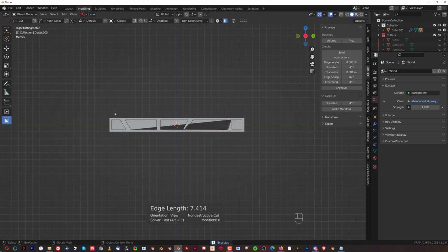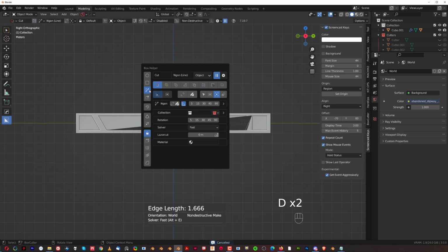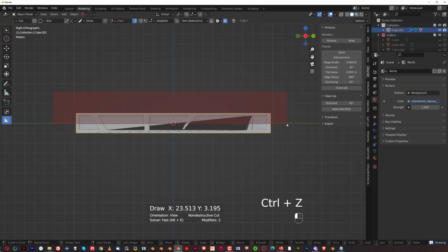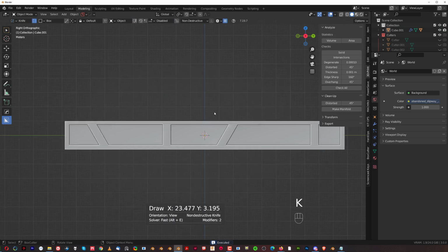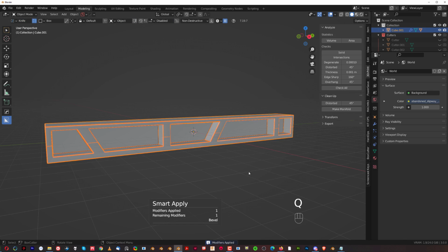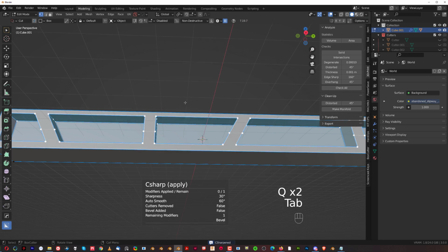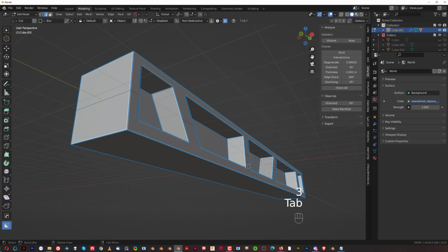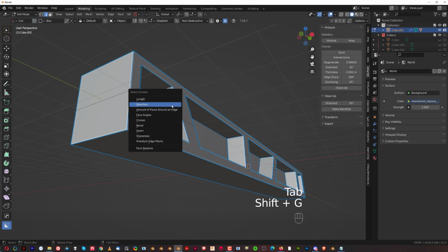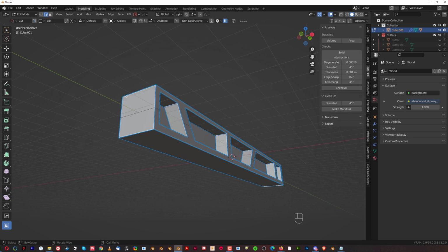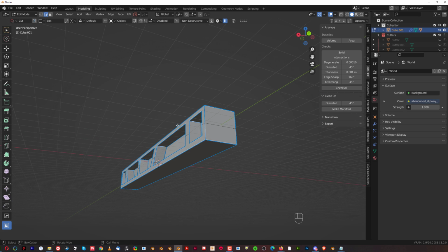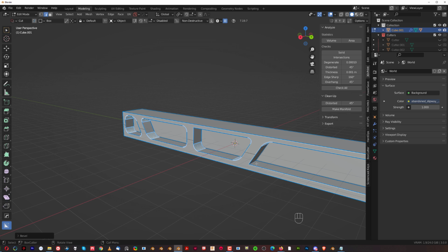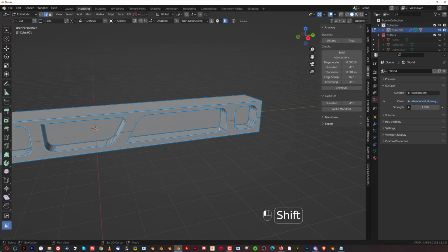And let's say, let's just cut it through, so we're going to have a nice even connection here, because I think Blender is creating some crazy connections on my mesh. K with knife, and boom. I'm going to sharpen this, so let's multiply and sharpen this, which will apply sharp edge everywhere. Now you see that we have rogue verts here, so let's press 3 to clean it with machine tools. Let's click on this edge, Shift G, and select direction. Deselect these edges because we don't need them, right? And then we go into bevel, all of these inside. These for some reason didn't get selected, which is interesting.